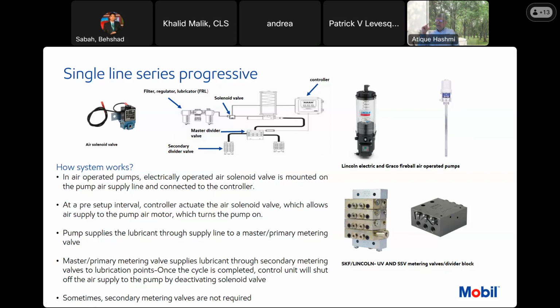But when you have an auto lubrication system on some components, for example, spray on open gear lubrication, you have spray nozzles as well. So in that system, air is supplied not only to the pump, it is also supplied to the air nozzles. But if you don't have air nozzles, then the only component which is getting air or running on air is the pump.